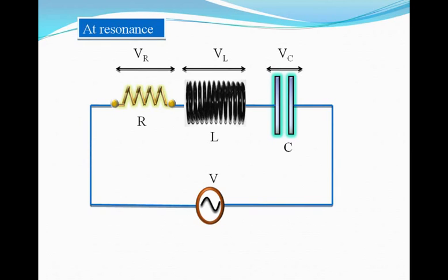So we can simply say, tan 45 degrees is XL minus XC divided by R. We can use some formula like that. We can draw the phasor for impedance, resistance and 45 degrees, and we can somehow use the formula tan phi is XL minus XC by R to calculate the value of omega. The problem is that in this case L and C are not given.